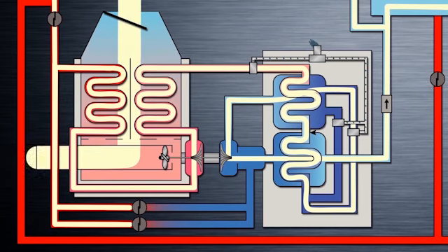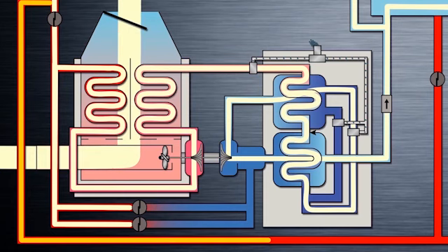This temperature is mostly unsuitable for the comfort of passengers and flight crew. Therefore, some form of warmer air must be mixed into the conditioned pack air. This warm air is known as trim air because it essentially trims the pack air temperature to make it more comfortable. The trim air pressure is regulated for the flight deck, forward passenger cabin, and aft passenger cabin.